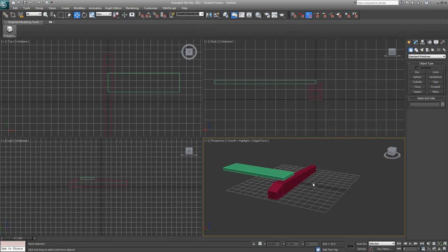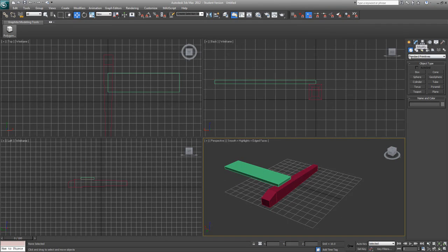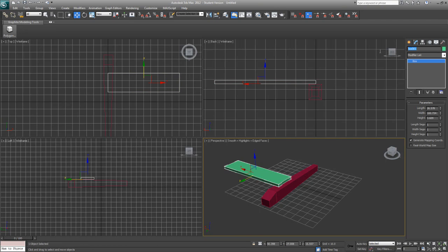So let's go up here to the Edit tab. I guess that's the Modify tab. I'm going to select that wing. And other parts other than the fuselage in RealFlight need to be named with a tilde CS underscore prefix. And a lot of parts will have required names. Since this is on the left side of the plane, it would be the left, L for left, M for main, and W for wing. This would be the LMW.